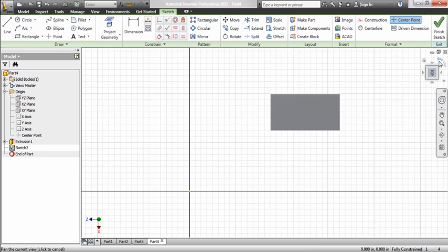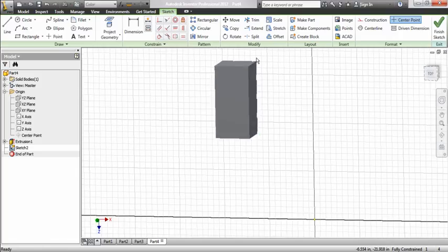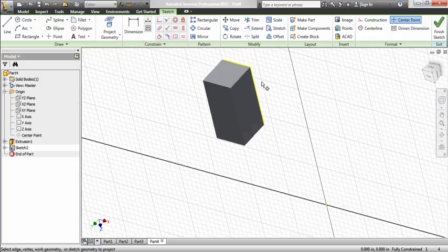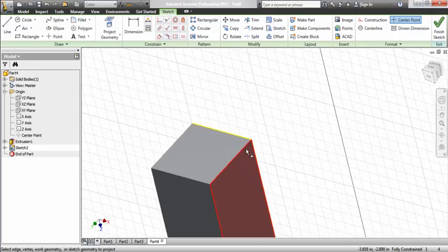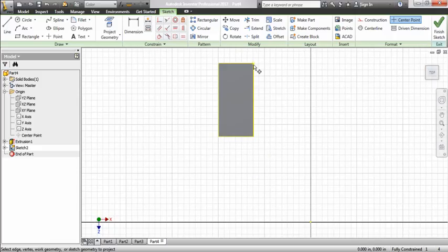and I'm going to rotate this around. Okay, right now I do not have the borders of this drawn onto my sketch, this piece right here, because I didn't draw directly on the face. So if you're going to draw on the origin plane again, what you have to do is go to Project Geometry. When I click Project Geometry and select this rectangle, when I go back to my sketch, notice that there is now a yellow border. So I now have a yellow border around my piece. That's going to be really handy because now I can lock onto this line.